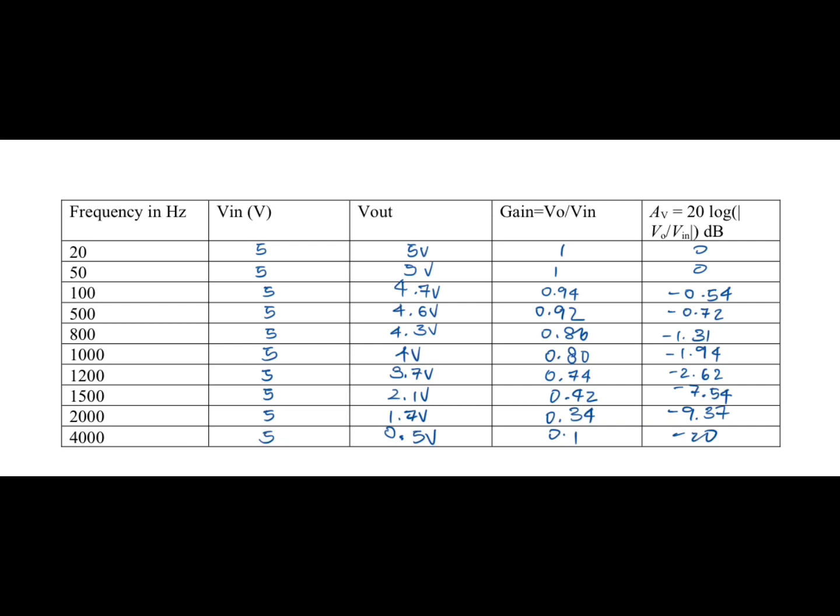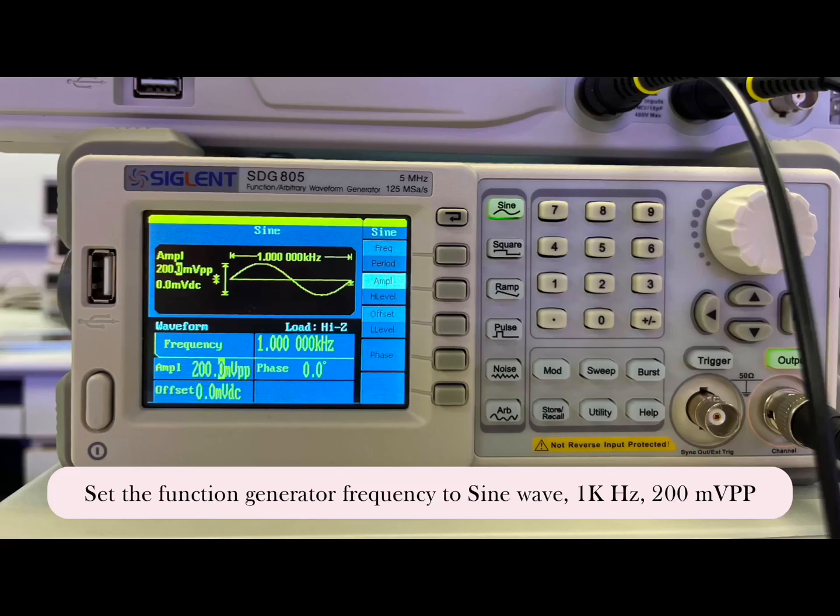As mentioned earlier, when frequency is below 500 Hz, the amplifier will be at unity gain. However, in this case, unity gain is not applicable as frequency is set at 1000 Hz. Hence, there is an output voltage drop from TP3 to TP4.